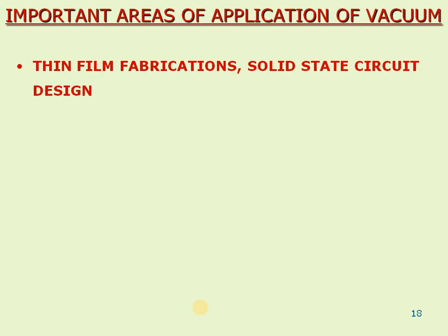For example, you form a film of aluminum. Suppose the space is filled with oxygen, hydrogen, sulfur, like that. What happens? This aluminum may react with the sulfur, may react with oxygen, they may form oxides, sulfides, carbides, like that. Then the film will be obsolete. It cannot be used for the purpose which it is intended. Its intended purpose may not be fulfilled once they form. So the space in which the film formation takes place should be free of any gas. So we need a vacuum.